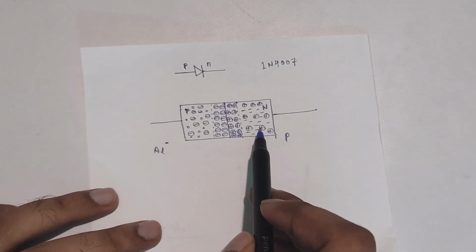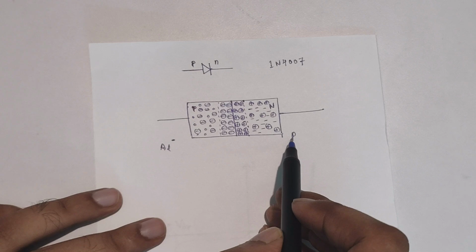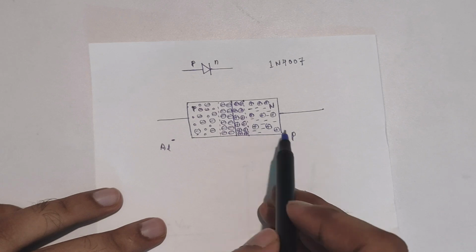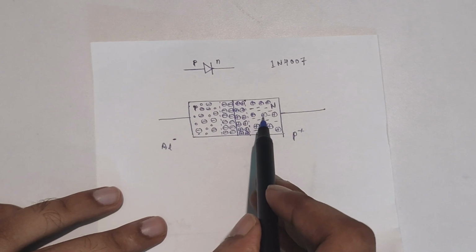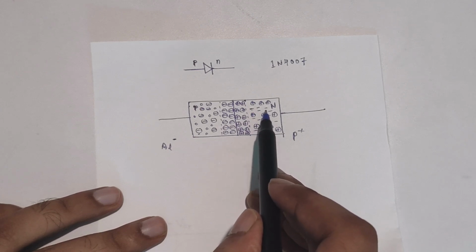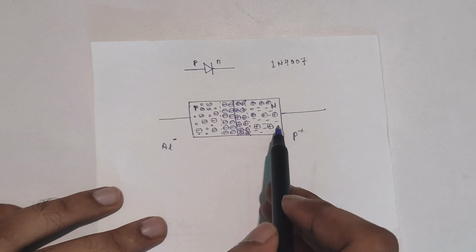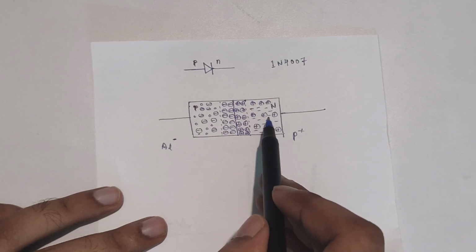When the silicon substrate is doped with phosphorus, it becomes an N-type substrate. Why? Because phosphorus has 5 electrons in its outermost shell, and it will release 1 electron in order to complete its octet. So when it releases an electron, it actually becomes a positively charged ion. I have denoted this phosphorus ion as a positive encircled, and these negative charges that you can see here are the electrons released by a neutral phosphorus atom. When it releases an electron, it becomes a positively charged ion, and the electron floats around the substrate, that is the N-type substrate.